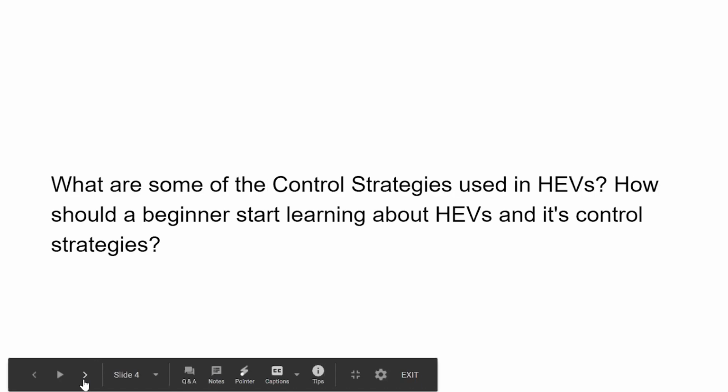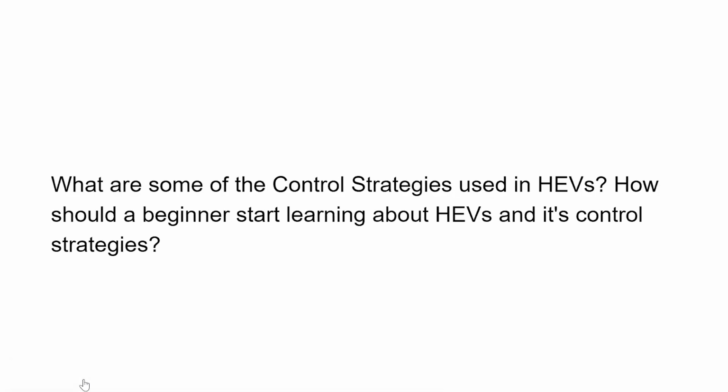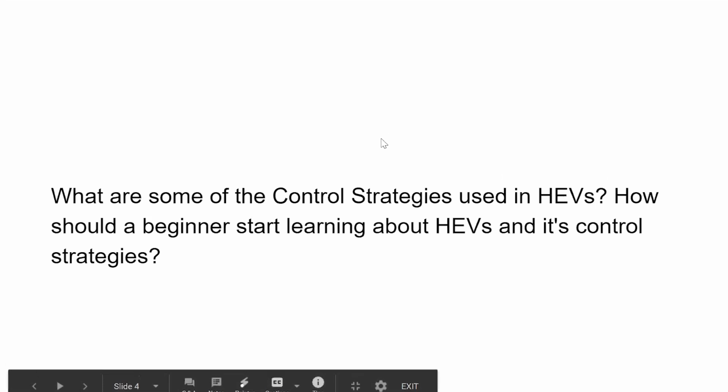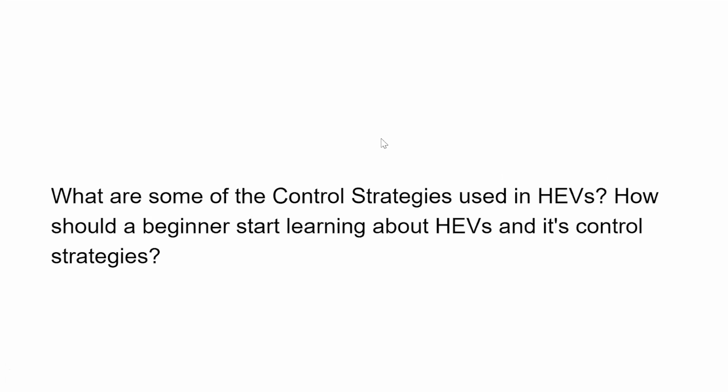What are some of the control strategies used in HEVs? How should a beginner start learning about HEVs and its control strategy? So there are mainly two control strategies that you can learn as a beginner. One is charge sustaining and the other is charge depleting. In charge sustaining, you have your battery at a certain state of charge, and the control strategy tries to maintain the battery at that particular state of charge.